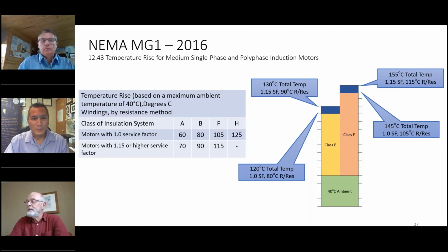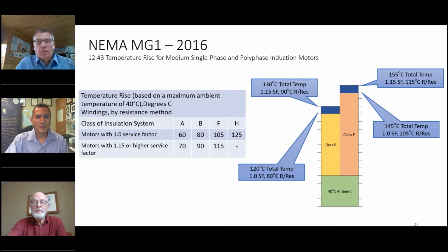The next one is from Anurad Chowdhury, and they're asking, what is the criteria for deciding combined VFD testing with motor? If I understand that question, there is something called a string test. Very rarely is a string test required or requested for your common garden variety motor VFD applications. String tests can often be done, and may be requested at great expense, on critical applications on mostly large machines.